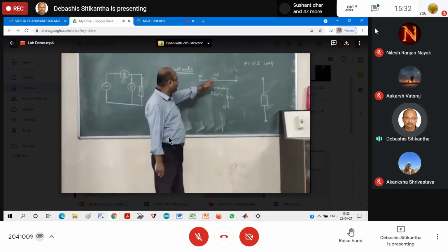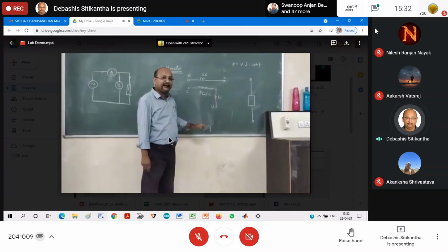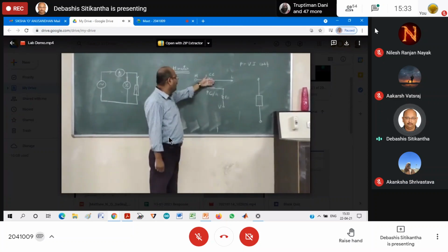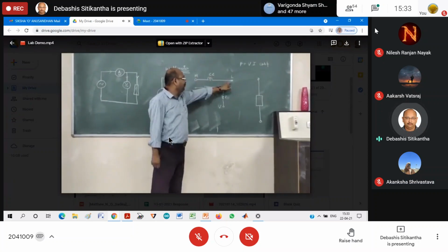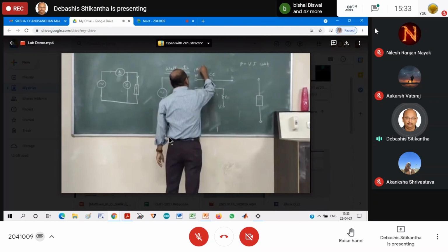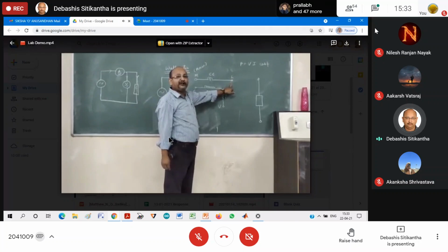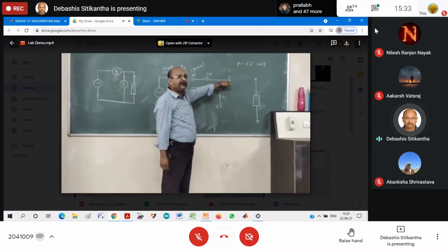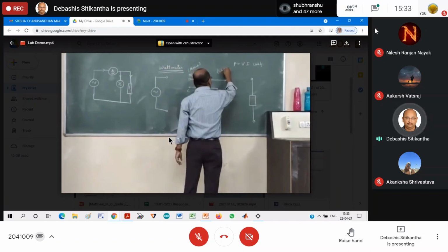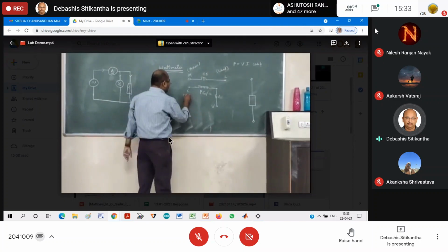So I have these two sets of coils, and here I have a resistance to limit the current flow through this parallel path. So how am I going to connect this wattmeter? In the wattmeter, you have terminals M and L. What is this M? This M represents the main point, or mains. What is this L? This is the point to which you are going to connect the load. That is why it bears the capital letter L. So this L point is for the load. What is the C? The C is the common point. I will tell you why it is known as the common point.